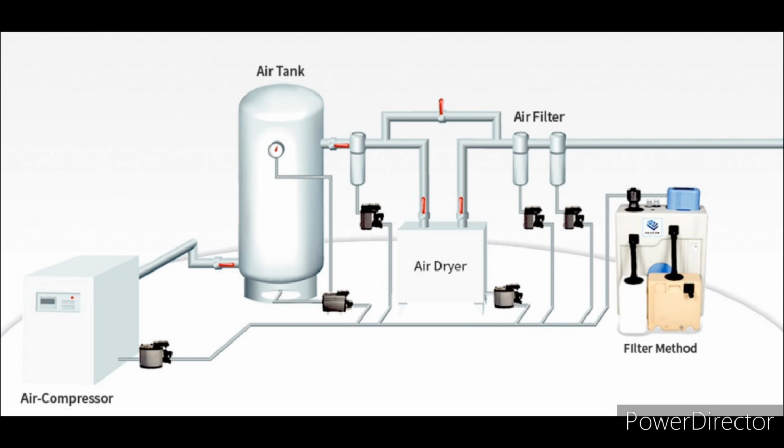Okay. So should I leave the drain valve open on my air compressor? It is important that you drain the tank every day and leave the drain valve open if it is not in use for some time. Doing so will let all the moisture drain out and reduce the chances of corrosion.